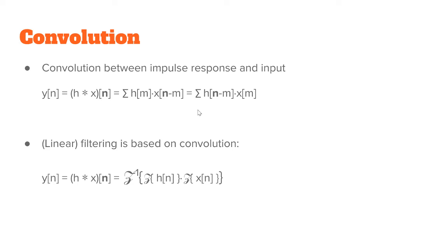So basically, this is your transfer function. So the transfer function is actually quite a tangible thing in the digital domain. It's just the Z-transform of whatever comes out when you put an impulse in the system.